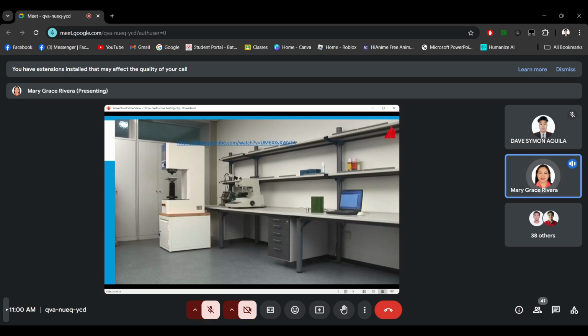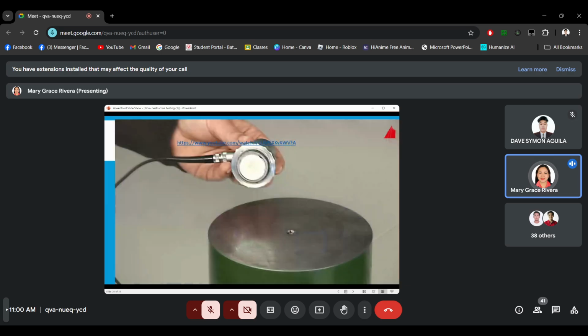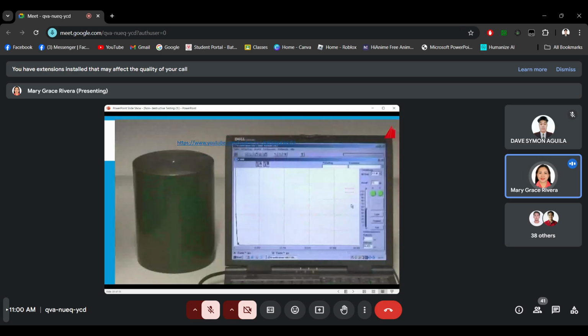In our laboratory, there's a green painted steel cylinder to be found. It contains artificial defects which are invisible from the outside. To track down the defects, the material tester uses the pulse echo method. This is how a typical probe looks. Under the bright wear plate, a piezoelectric disc is installed. It can transmit and receive ultrasonic pulses. The computer operates the probe via a plug-in card and power electronics. On the monitor, the intensity is plotted upwards and the time is plotted to the right.